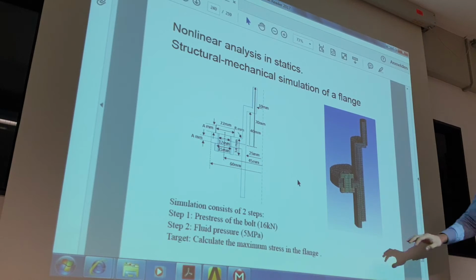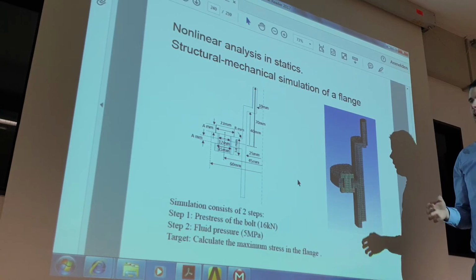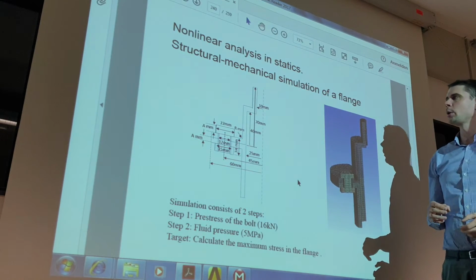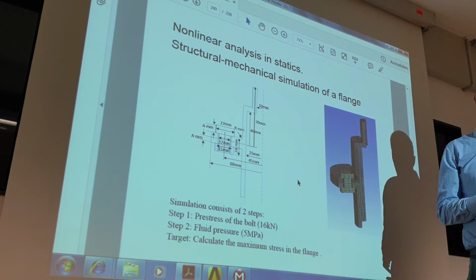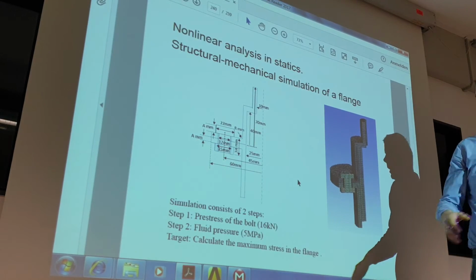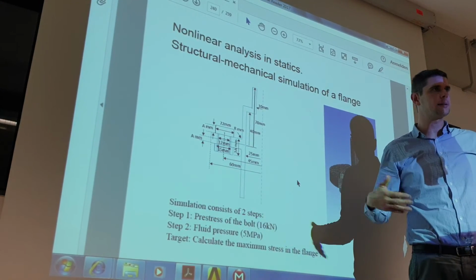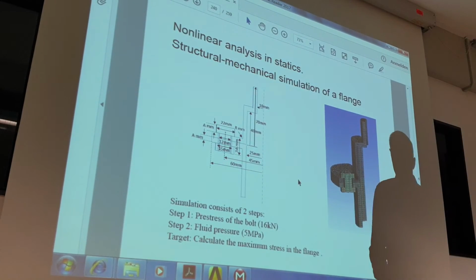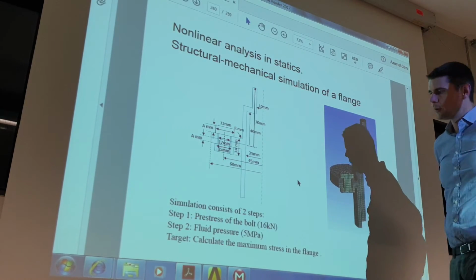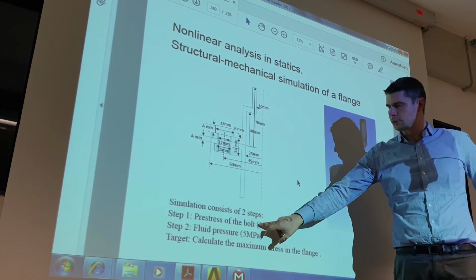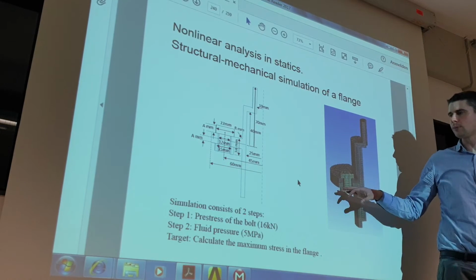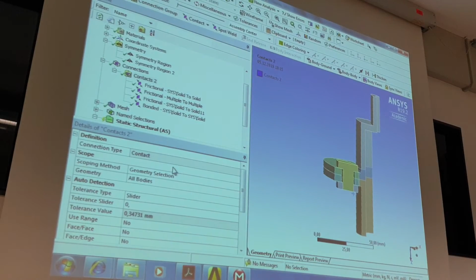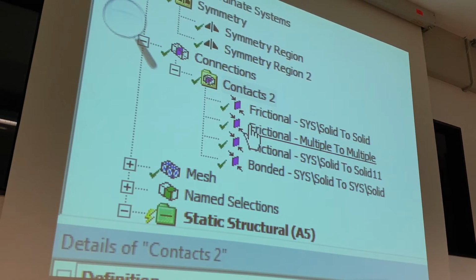First, we have 2 steps of simulation. It's always 2 steps. We have pre-stress always separate, yes? Normally, our question is this fatigue, yes? Fatigue, I have 1 million times this pressure load, 0 to max, yes? And my pre-stress is always the same, yes? Then I need to separate this pre-stress. Always. Okay, and it's easy to control. Is it always correct? Then we have 2 steps in the simulation, and we need to say it in the program.